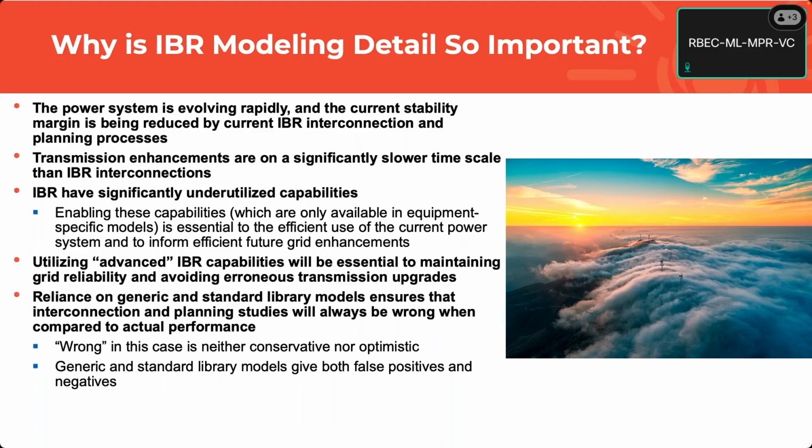As the margin goes away, advanced features are going to be much more important. We may see, as the stability margin goes away because of maintenance or other things, that the short circuit ratio or system strength at a specific plant could vary wildly. That means either when those maintenance events happen, you redo a study, or there are features like I mentioned yesterday, where if the system strength changes, the IBR plant controllers can measure this and change their gains to be stable at both those operating points. But we'll never be able to study that without a real detailed model.